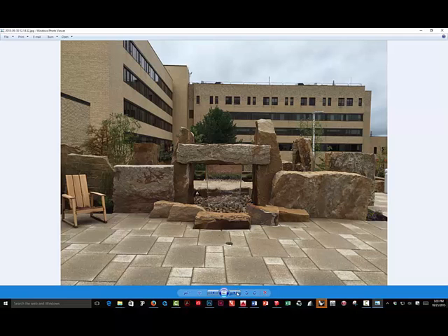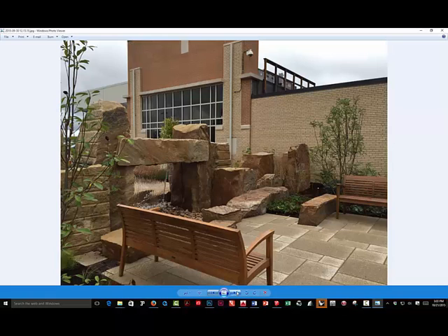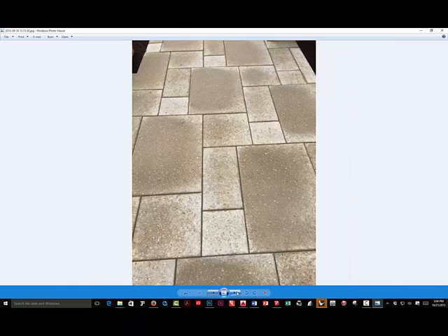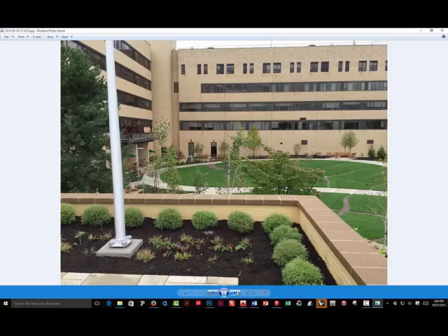So this initial part of the assignment is going to be just about getting the forms on the ground plane from AutoCAD to SketchUp and creating a terrain model from contours that are in the AutoCAD drawing, which already have elevations on them, and then draping or projecting those forms onto a landform surface. Also going to introduce the use of Topo Shaper, although I think I mentioned and we've used the terrain from contours tool. It's one of the sandbox tools that comes with SketchUp.